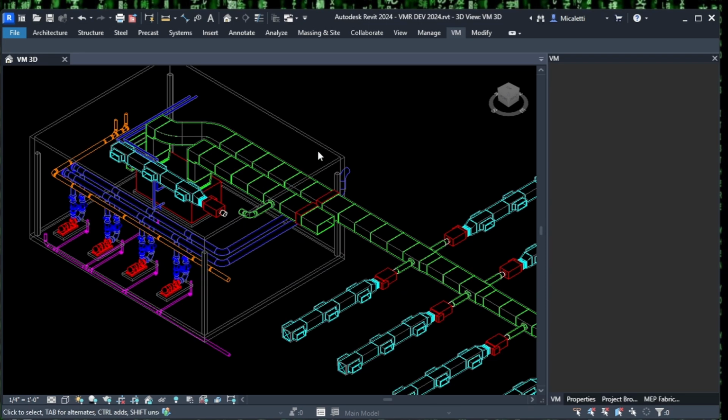Now what this does, it's going to find any intersections between other modular elements, and it does work with linked elements. But what you're going to want to do is heavily use view filters to filter out anything in the link or anything in the model that you don't want to sleeve. So I'm only showing, for example, structural walls. I'm not worried about sheetrock walls right now. Just show me all the structural walls, show me the slabs, show me the roofs, and let me make sure I get our openings in those things.